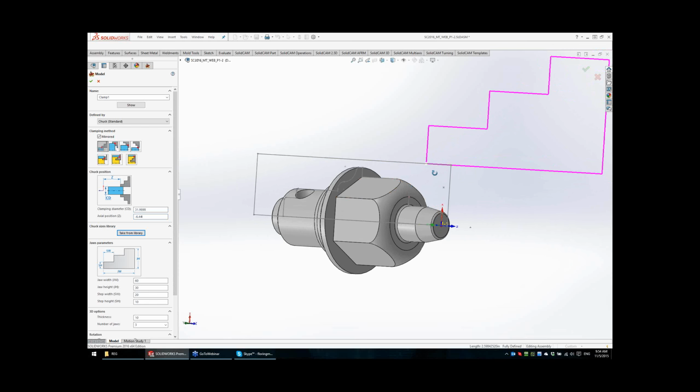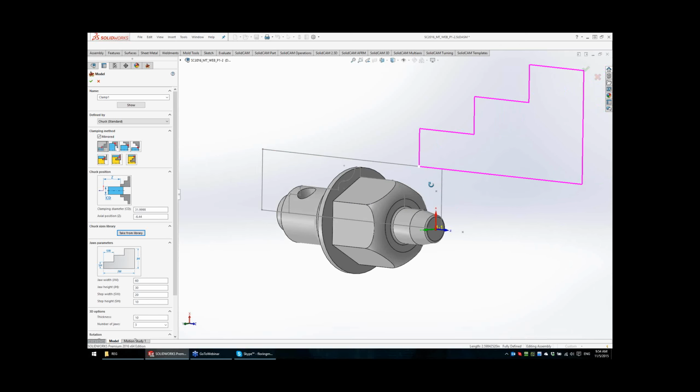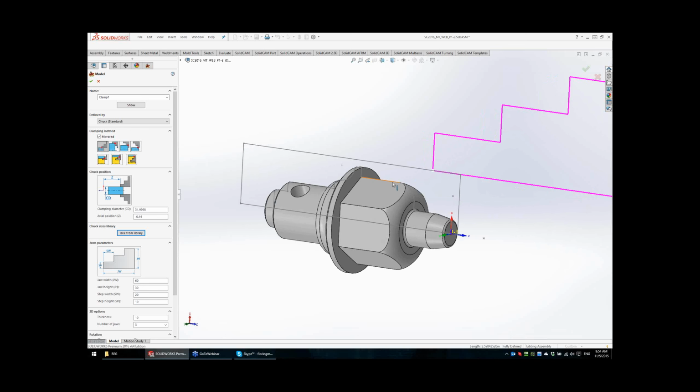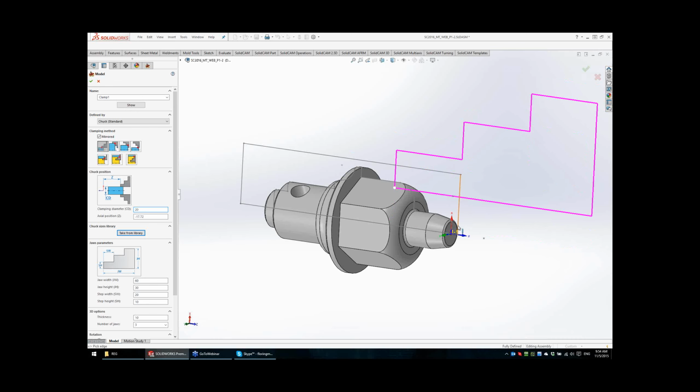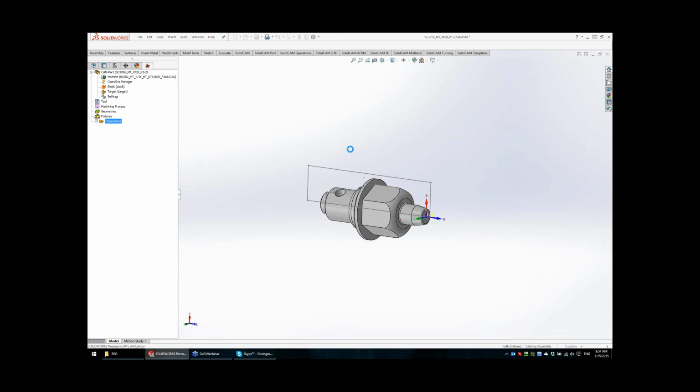The clamping diameter is important, because I want to see the jaws exactly on the diameter where I want to catch the part. As you can see here, we have those sharp edges, but I don't want to catch it here. I will rotate the back spindle and the jaws to catch the part on this hexagon, on the surfaces. So this surface is somewhere around 20 millimeter diameter.